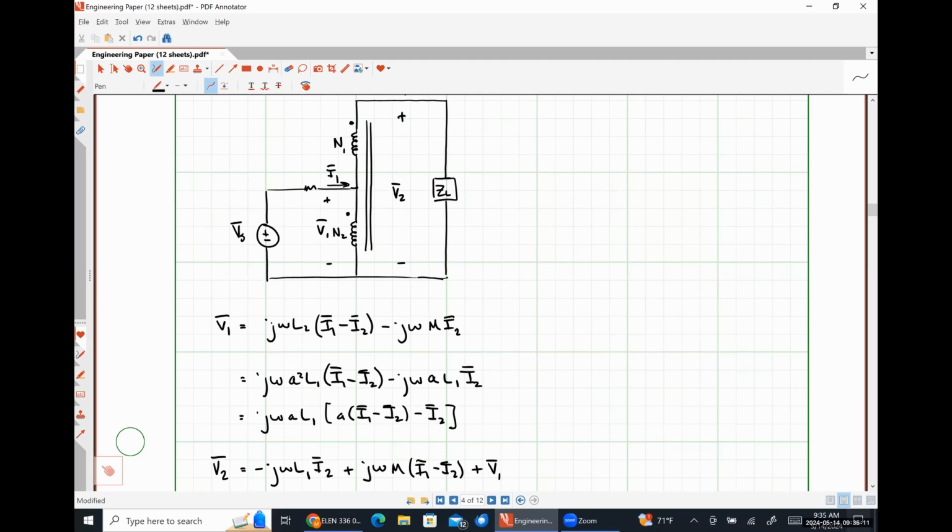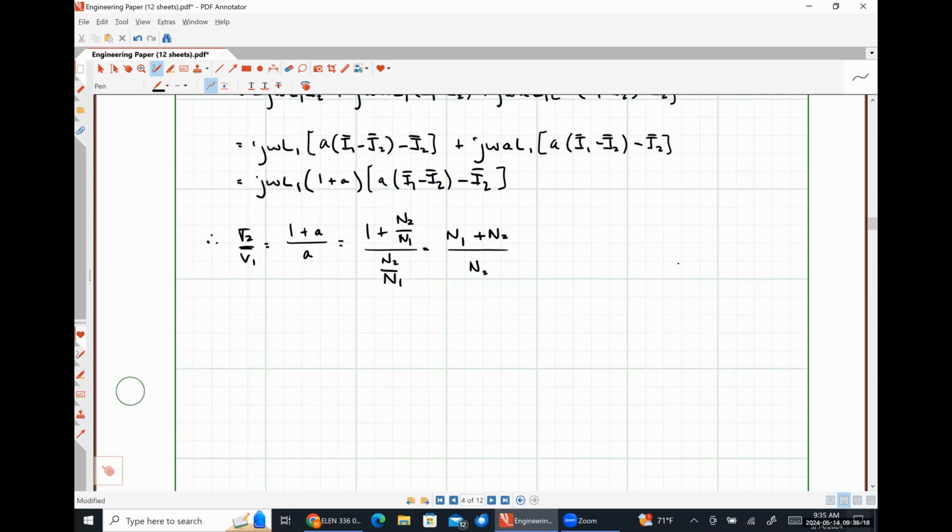Right? So we have step up. Actually, just while we're at it, our current ratio, I2 over I1, is simply V1 over V2, or N2 over N1 plus N2. Literally just the reciprocal of what we had before. Currents behave exactly how we expect them to behave.